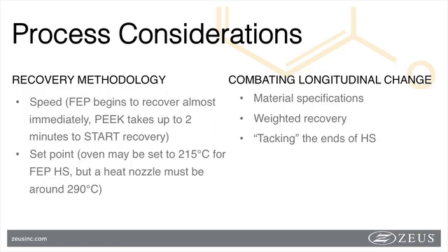Speaking of the temperature of recovery, the set point of your heat source may not, and generally will not, correspond to the exact temperature material is experiencing. Mandrels are generally a heat sink in the system, which lowers the overall temperature of an oven, for instance, when introduced inside of such. Preheating the mandrel may overcome such a drastic temperature dip.